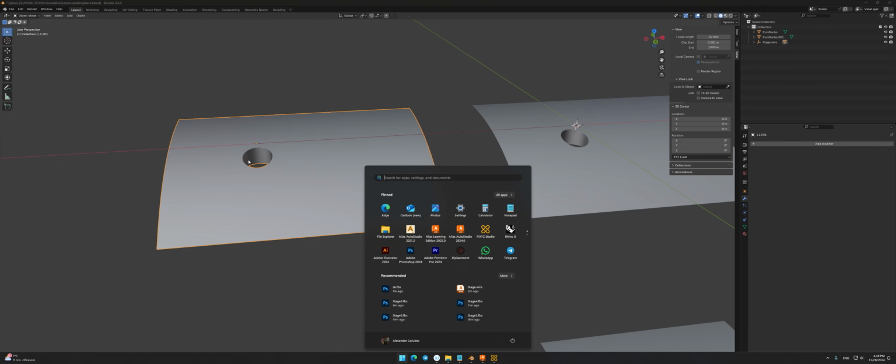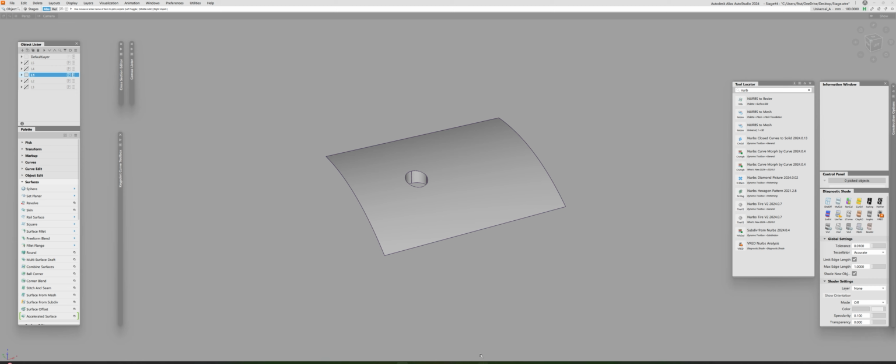Now, as I said, Pixyz is not the only tool you can use. There are a few others. I tried CutFix, and it's pretty good, and Polygonica, I never tried, but people said it's good. HOOPS is pretty good as well. What I will encourage you is to not use the standard built-in functions of Alias. I heard that in 2025.1 they made some adjustments to the tessellation, to the exporter, and I checked it out, and no, it still runs badly. So don't use it. If you're working with Alias, do not use built-in exporters. Use only external exporters.